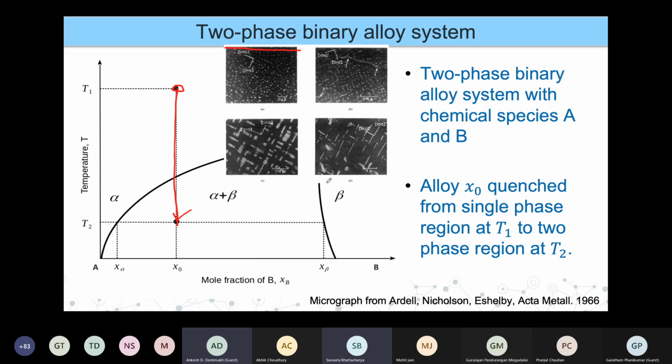This is something that is there in superalloys, and superalloys are in general a very important class of alloys. And not only superalloys: if you look at aluminum alloys and titanium alloys, precipitation is one important process. We are looking at diffusion controlled precipitate growth and coarsening in this part.